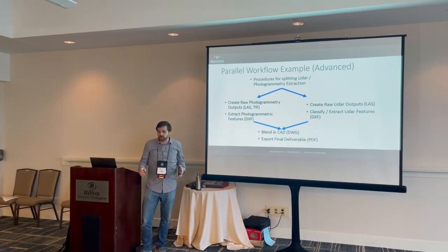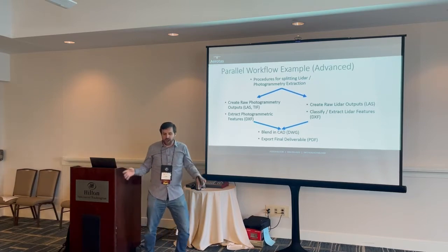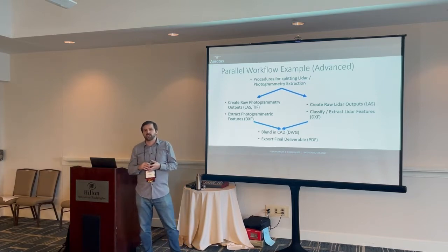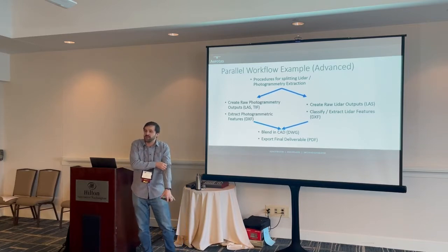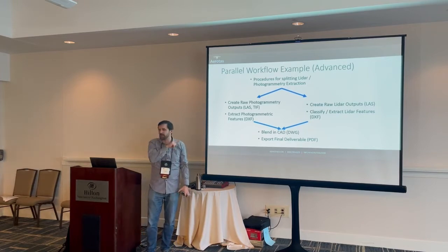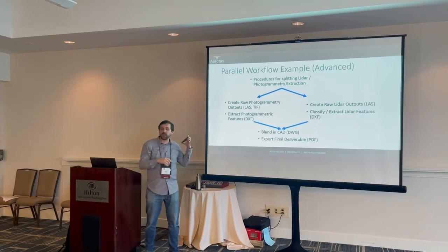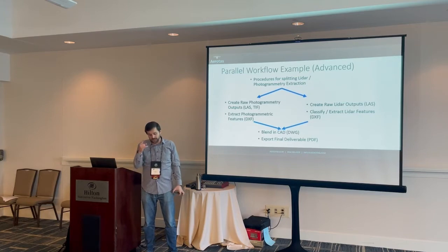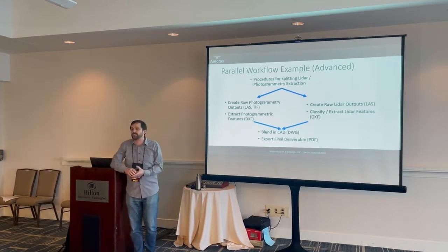So for our procedures, what we have is basically a book of rules to describe when the vegetation is so much that we will get it from LiDAR versus when we will get it from photogrammetry, such that the LiDAR team is able to look at a project site and say, yep, here are going to be the vegetated areas that we need to extract and get clean LiDAR surface data out of. And the photogrammetry team will look at the photogrammetry model and say, those areas are too highly vegetated, I'm going to ignore them and only draft the hardscape data.